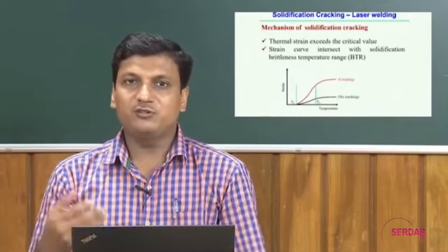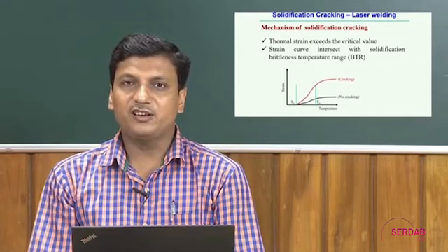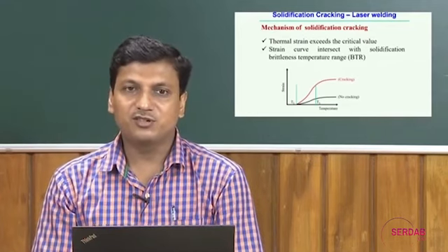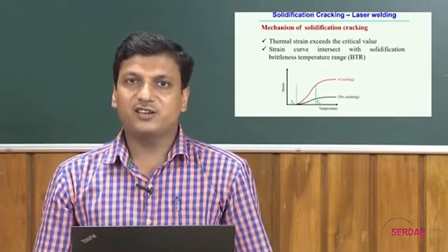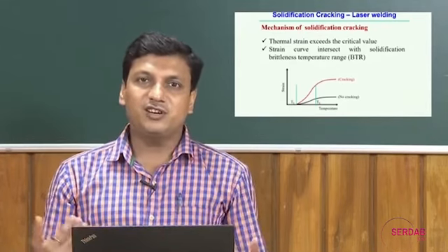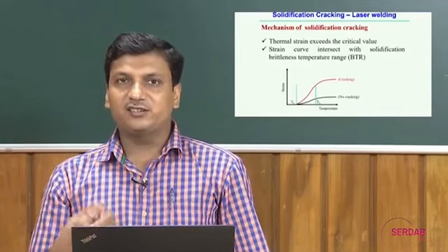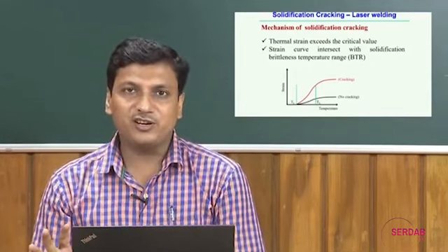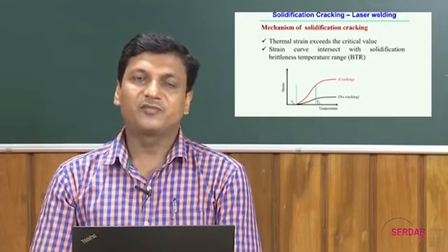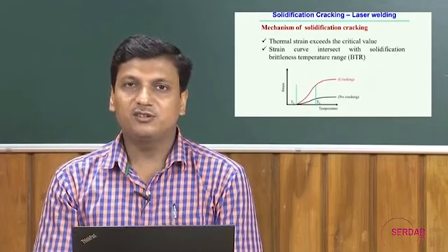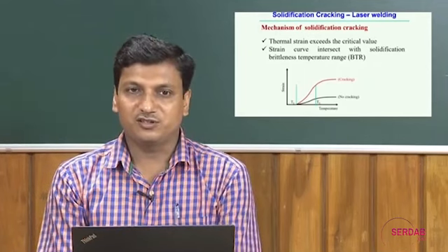If we look into the mechanism of solidification cracking, it is very specific to the laser welding process. If we look into the temperature and strain, when the thermal strain exceeds the critical amount of strain, that strain induces the cracking phenomena during solidification in the laser welding process.